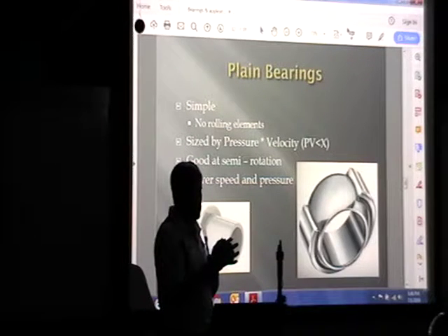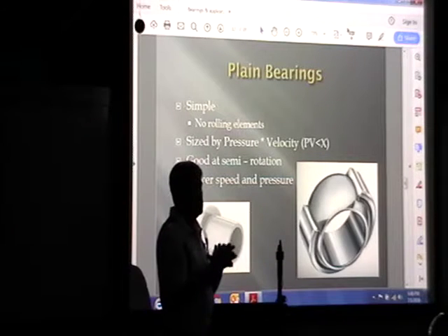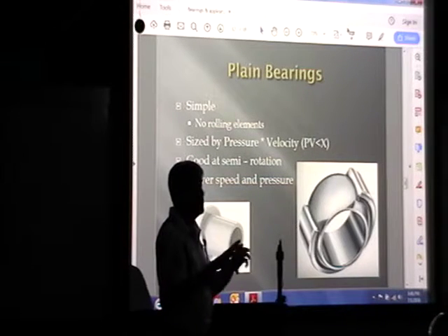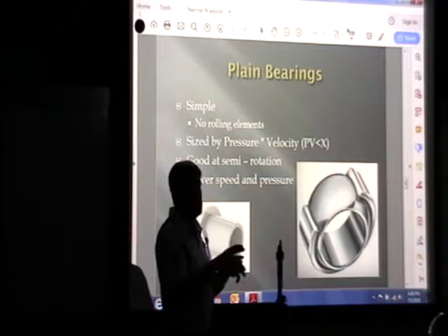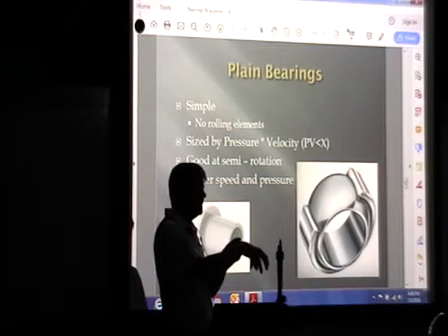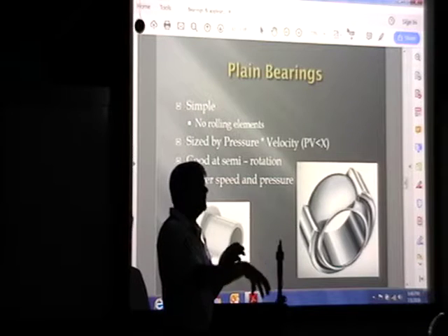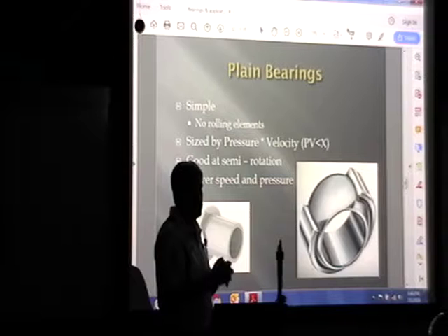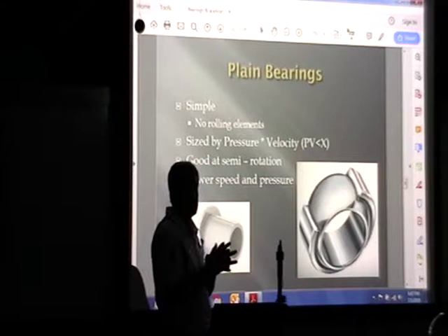If you just want a bushing, like a bronze bushing, that would fall in the plain bearing category. We used some bronze bushings in our extended wheel actuator this year because we did not have a full rotation there and it didn't have a lot of load when it was rotating. Now it had a lot of load when it was locked up, but where you need the bearing is when things are actually trying to move. That's what you want to compensate for. Any questions on plain bearings?